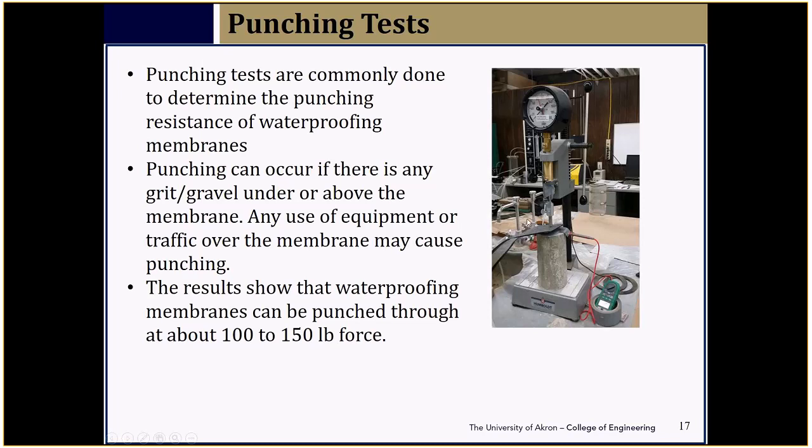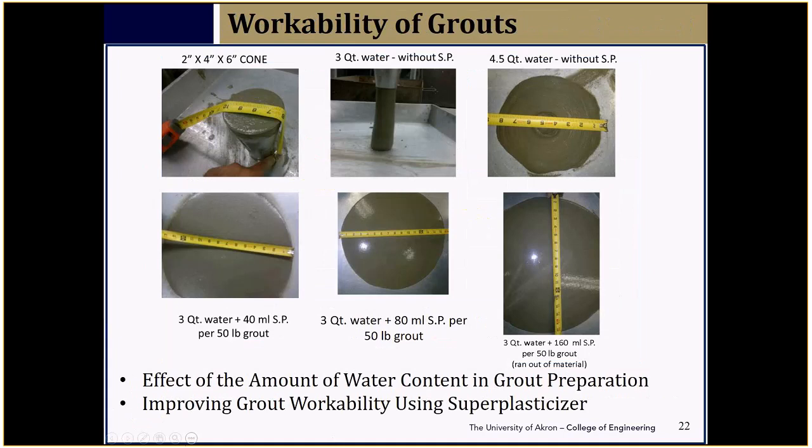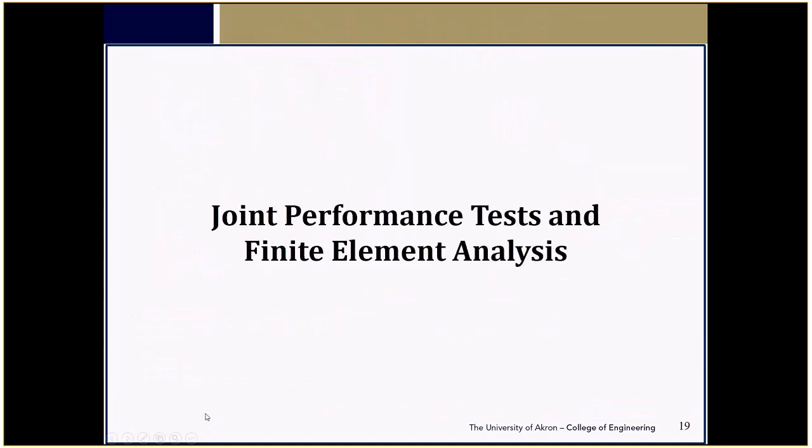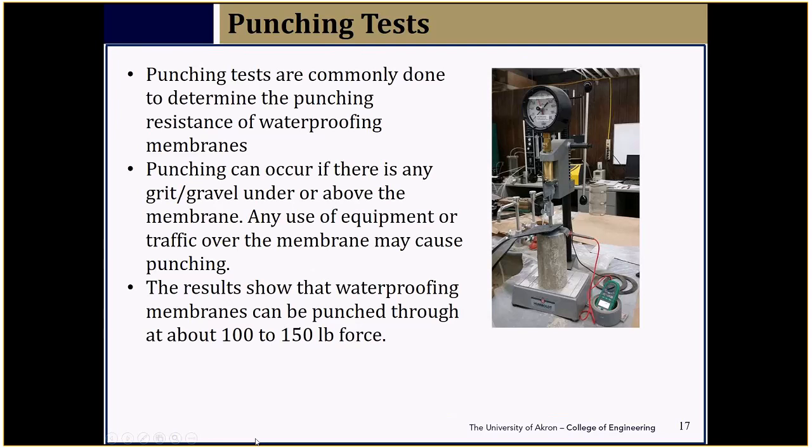So my student came up with this mechanism whereby we have an electrical circuit here, and we have a defined load applied through a small pointer. Anytime the pointer punches through the membrane, you complete the circuit, and it makes a sound, and then we are able to figure out when there is punching through the membrane.